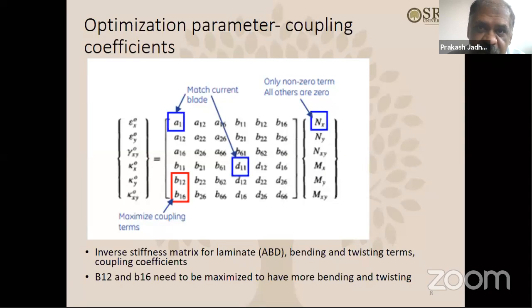Okay. So if you have a neutral axis, below the neutral axis and above the neutral axis, the layers should be same. So symmetric layer and unsymmetric layer. So if we forcefully build unsymmetric layer in the composite, it creates some kind of warping, twisting in the part when it is subjected to some loading.